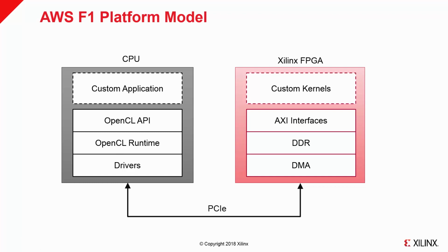OpenCL is an industry standard providing clear semantics for parallel computing. The OpenCL runtime is responsible for managing and servicing the various accelerator requests sent to the FPGA. At the lowest level, the drivers handle the PCIe transfers between the two devices. The FPGA sits on the receiving end of these PCIe transactions.